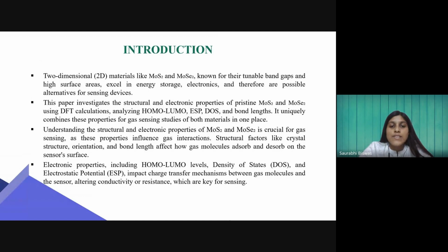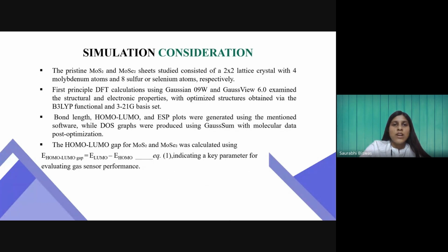So the structural aspects like the crystal structure, the orientation, bond length, etc., determine how the gas molecules adsorb or desorb on the sensor surface, which will affect in turn the sensitivity and the response time of the gas sensor device. Also, the electronic properties like the HOMO-LUMO, the density of states, the electrostatic potential impact the charge transfer mechanisms between the gas molecules and the sensing material, which alters the sensor's conductivity or resistance. So, therefore, these properties are very essential to be studied.